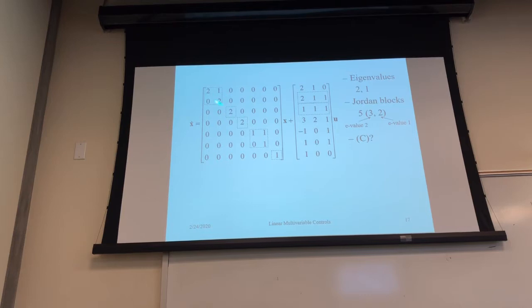So the first eigenblock, first Jordan block: the last row corresponding to WB, like here. For this Jordan block, the last row is also the first row, this one, corresponding to this 3 to 1. So you get a 3 by 3 matrix. We want to check if we can tell whether the mode for the eigenvalue is controllable or not. It is controllable if and only if the 3 by 3 matrix is full rank.